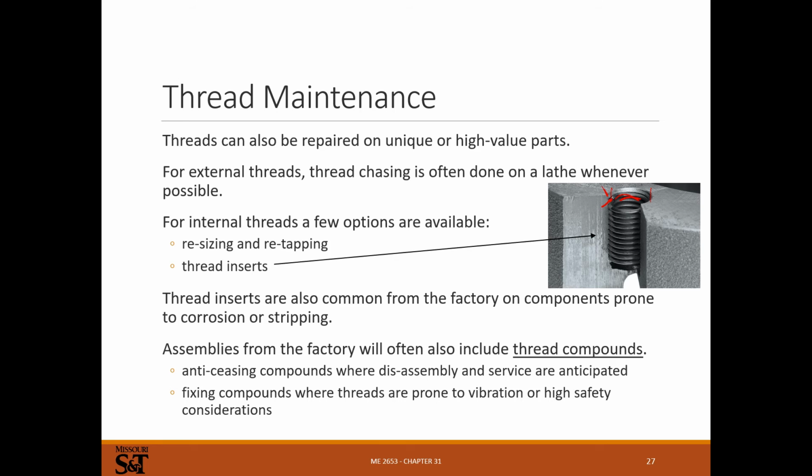So you usually buy sets for fixing; there'll be a set for fixing a 3/8 hole that'll have the drill size, the tap, and it'll also have the coils that go in. There might be some feature for keeping these things from rotating in the hole, for through holes. There might be some little tang that you can crimp into place and keep these things from rotating.